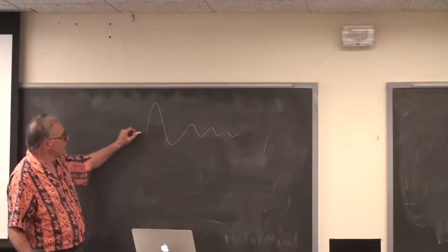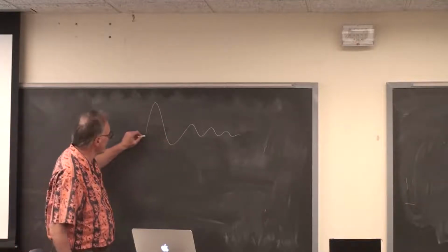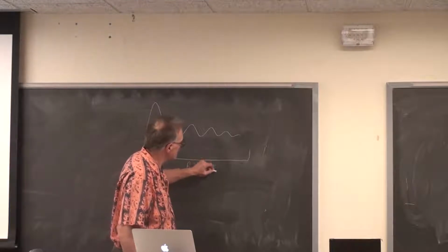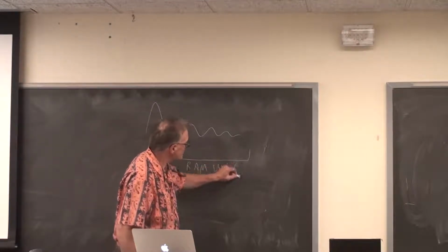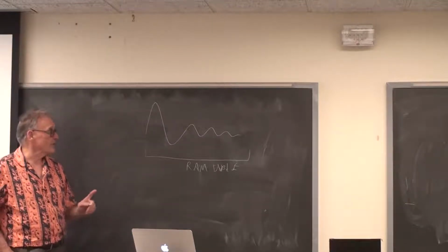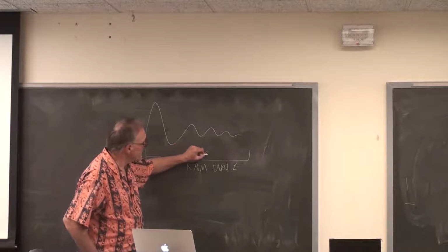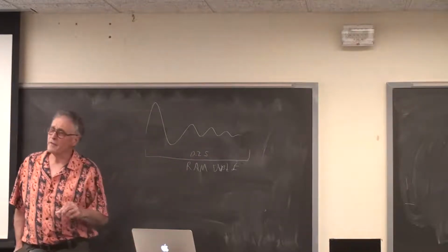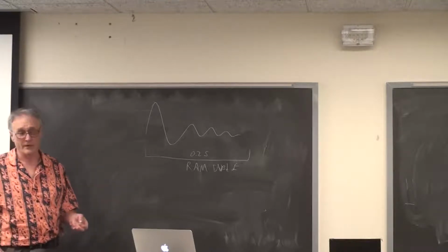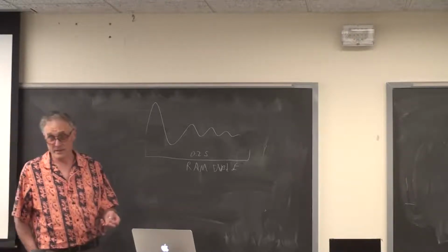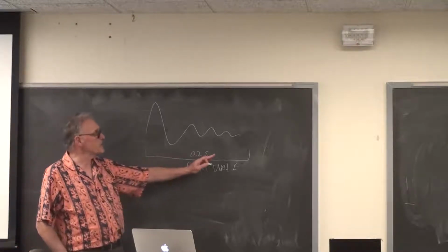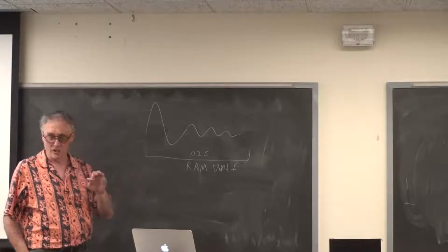What I'm going to ask you to do is to put the whole waveform into a table, a RAM table. So the whole waveform is going to be in the RAM table, let's say 0.2 seconds worth. You may have to slow down the synthesis rate in order to fit this waveform into memory. I doubt if you can put 20,000 samples in memory. I know you can't. So you're going to have to slow down the sample rate, maybe 8 kilohertz, maybe 10 kilohertz, but that's a detail.